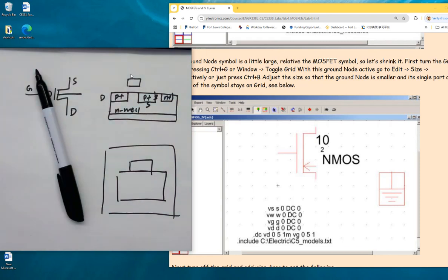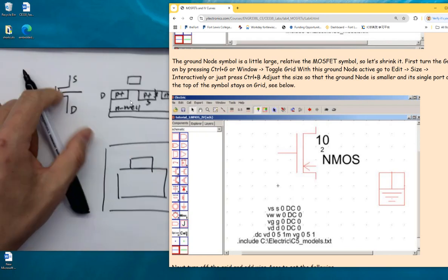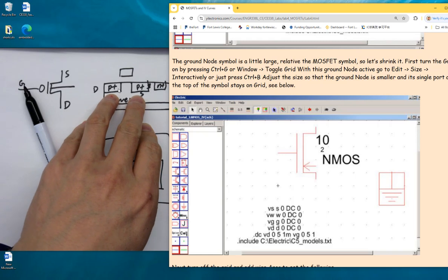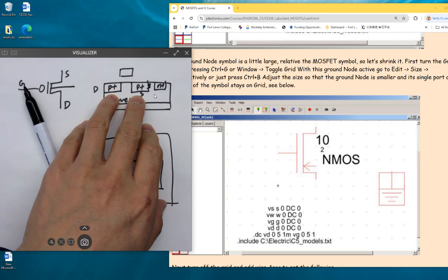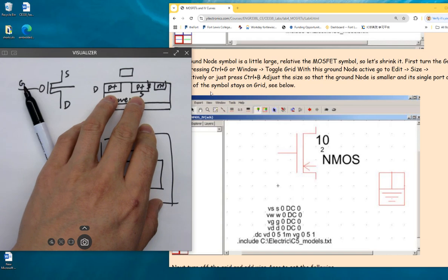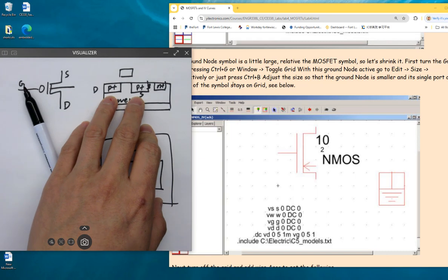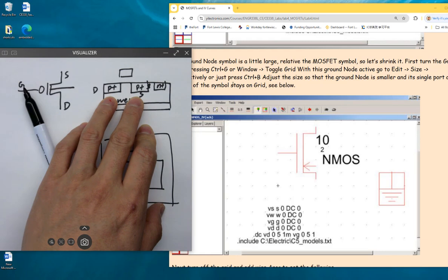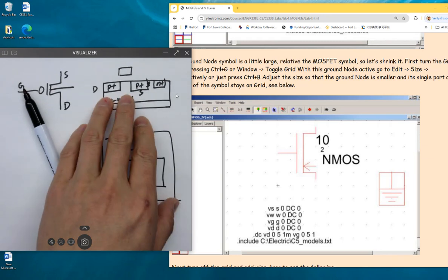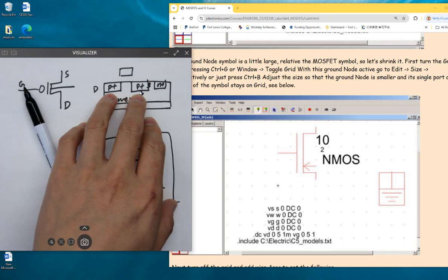Okay? And for the CMOS technology, since it's so old and so simple, there isn't any difference between source and drain. They are symmetrical. Same node, same material. But in some advanced node technologies, they may have a thicker drain in order to handle higher voltage. So there's a certain technology called C5 HV, I'm sorry. C5 HV is the high voltage C5 version. So that one has a thicker drain, so I have to use that terminal as a drain. But for this very simple technology, source and drain are symmetrical. They are the same node.